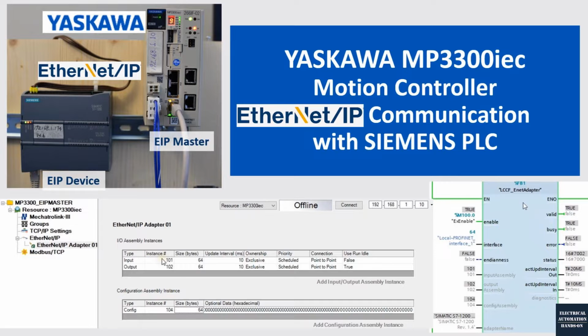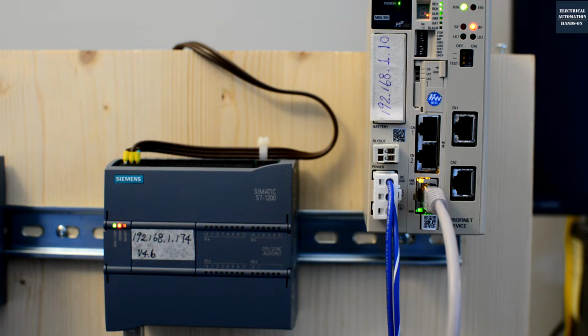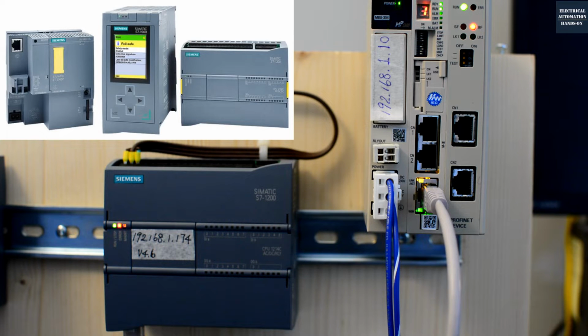I know it's rare to see a Siemens controller run as an Ethernet/IP adapter or device, but I will definitely show how we can use this. As we can see in the current hardware, on the Siemens side I'm using a standard S7-1200 PLC. If you are using the S7-1200F, the safety built-in controller, the method is the same.